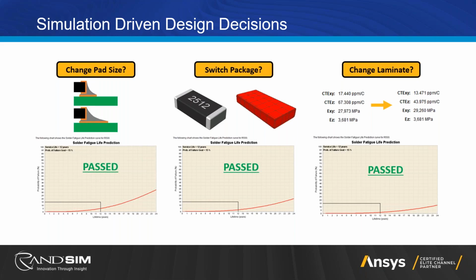So changing how you have the solder mask applied, or the type of laminate, or maybe the density of the copper, or changing some of the way that things are routed is going to have impacts on all these things as well. Some things also that aren't mentioned here would obviously be component placement. So how dense is it in a certain region, or, if we linked it to IcePak, how close is it to a very hot heat generating component? Things like that allow you to make the decisions prior to fabricating and ensure that your design works as you expect and is reliable.